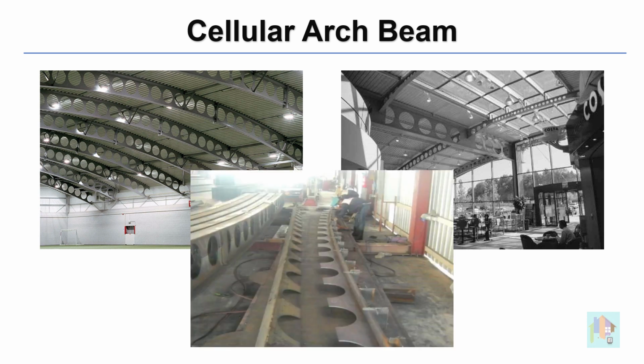For castellated beams, it is very easy to bend the cut pieces first and then weld them together as an arch. Bending a wide flange section is rather tough, so castellated beams are preferable for any arch type roof. I am not sure whether you have used these types of castellated or cellular beams in any of your projects, but these are widely used in several sectors.